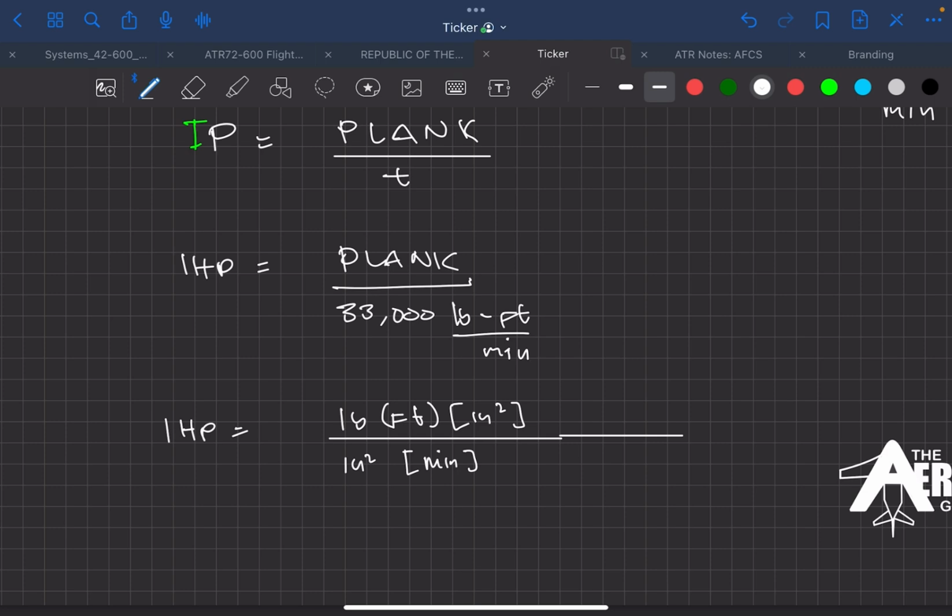And the number of cylinders, which does not have a unit. You also have the conversion here, lb-feet per minute, which has a time factor being divided, so we put it up. When you cancel out the units, all the units will cancel out, and then you have the horsepower.